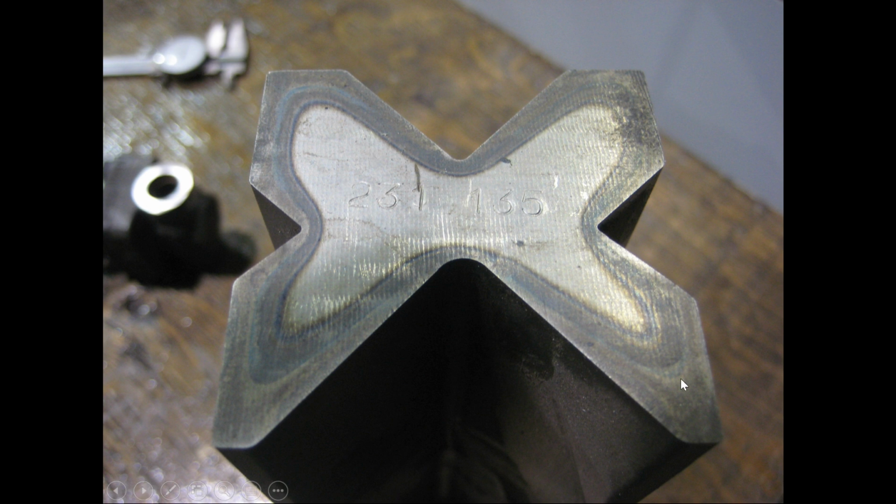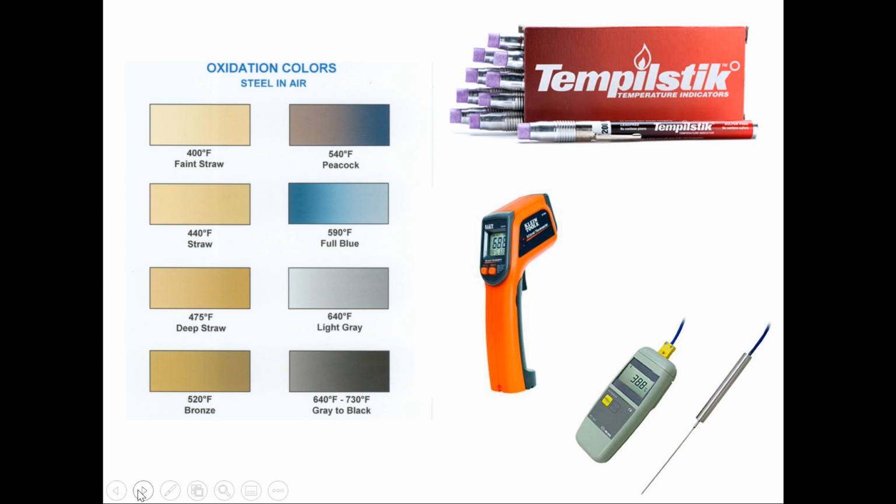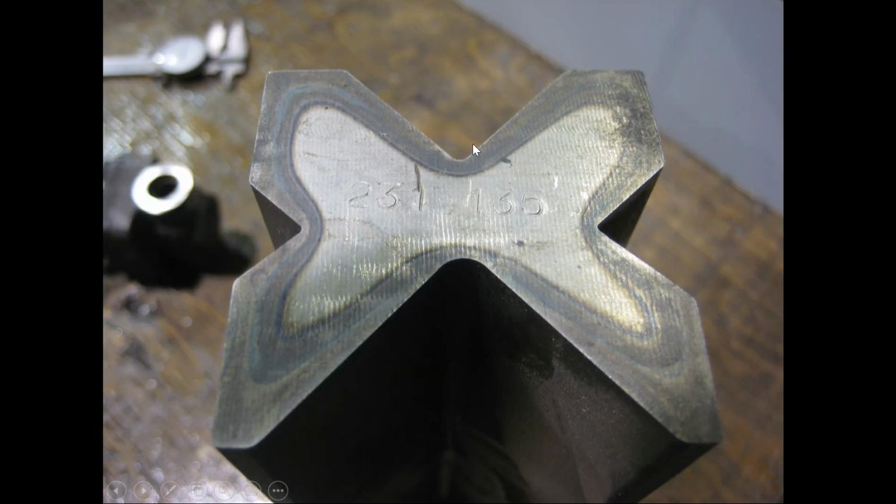I like this picture. This is actually a die off a brake press. And as we cut it, the heat started to come in at the edges and it showed color. And all these colors, as we've seen back here, actually mean something. So these colors freeze time for us as welders. These colors freeze time and show us how hot the temperatures got in the steel while it was being exposed to air. This was when they just threw it in a chop saw and started bringing it down. And this is where we ended up. And you could actually see the different colors and what they are.